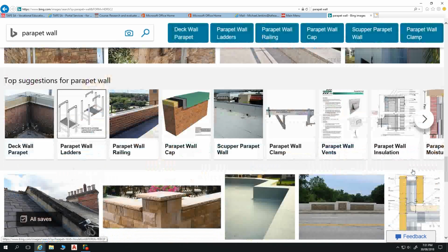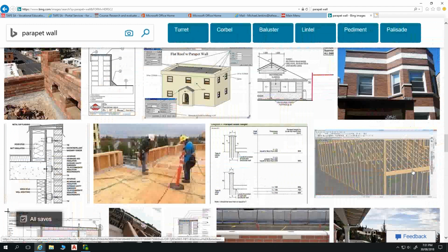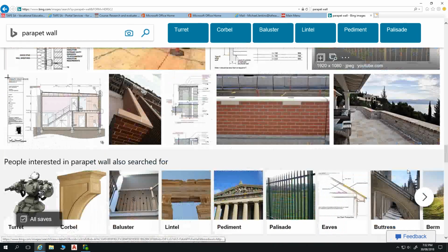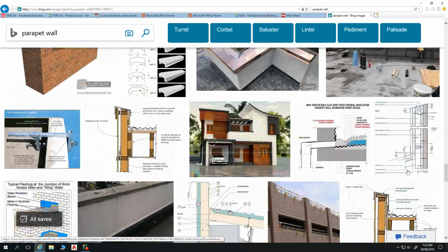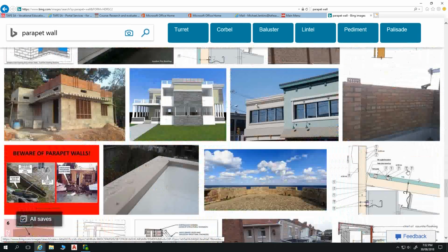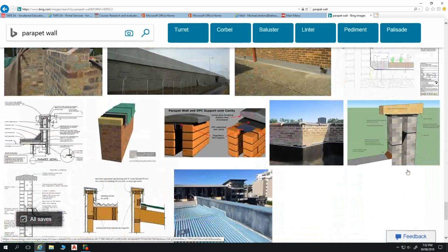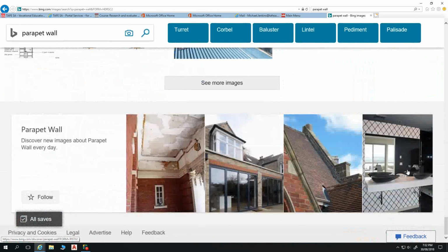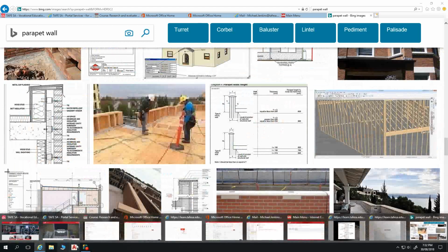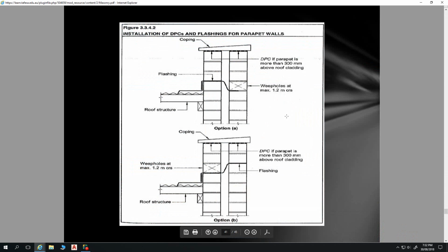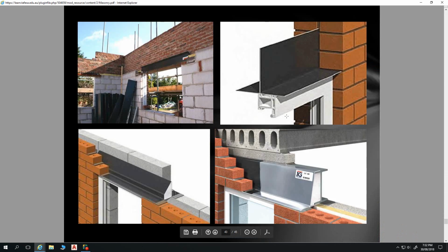That simply means though that you can't have an eaves gutter because you don't have eaves. So all of your water gets contained behind that parapet wall, so it's very important how that water is dealt with. And that's essentially dealt with with a parapet gutter, which is another form of box gutter. But yeah, there's plenty of scenarios where that happens in fairly standard residential construction as well.